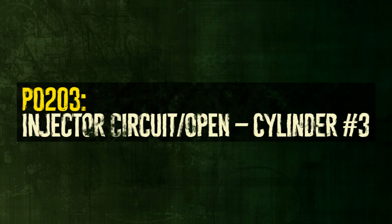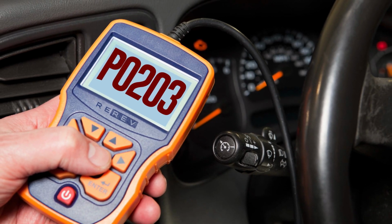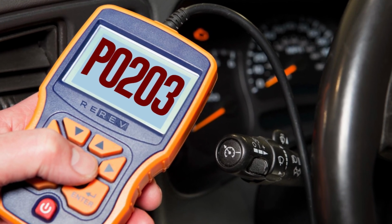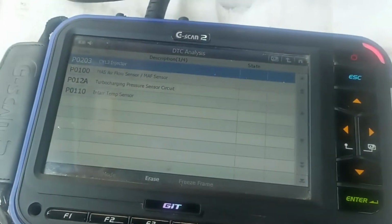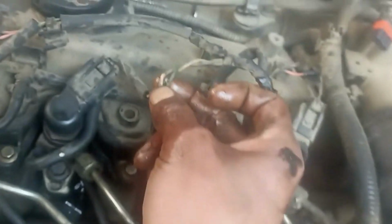A fuel injection system fault, or more precisely, a defined fault within the control circuit of a particular fuel injector, is indicated by the diagnostic trouble code P0203. In this instance, fuel injector number 3 on an engine is the culprit in question. This is a perceived fault because the number 3 injector circuit's irrational feedback has been detected by the affected vehicle's PCM, indicating a possible problem.